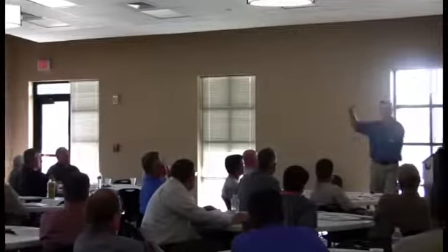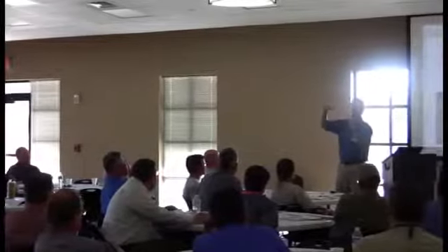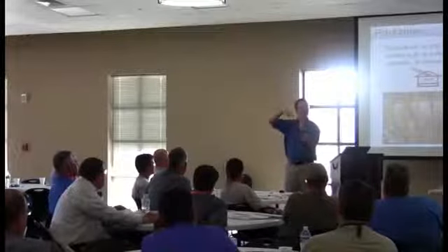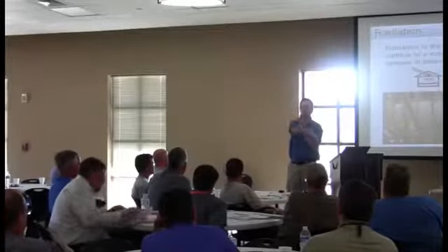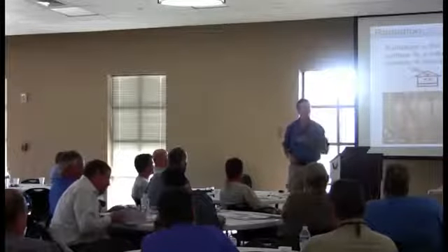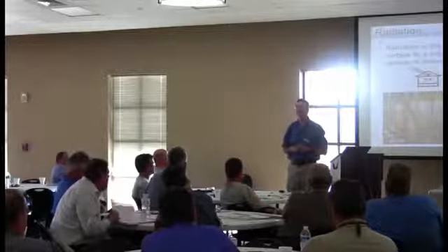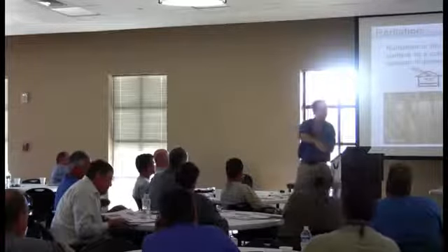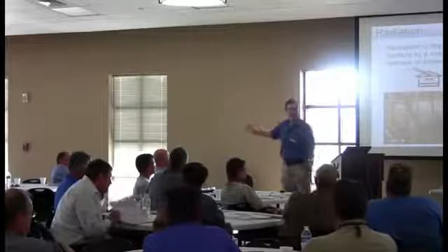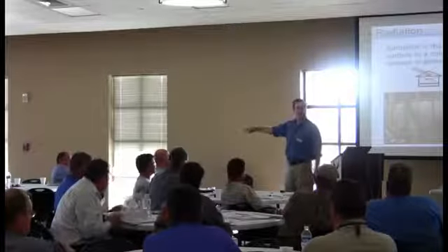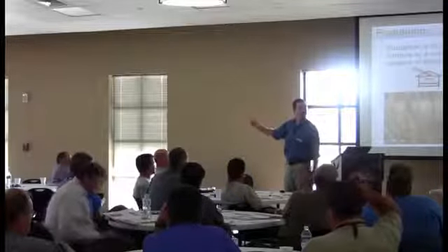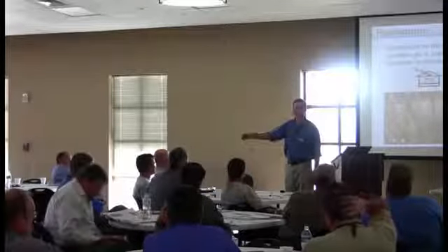When the sun hits a single pane window, some of the sun's energy is absorbed and reflected back, but most of the sun's energy is transmitted all the way through into the building. And in this case, the answer is 80%. 80% of the sun's energy passes through a single pane window. And so how many BTUs are getting in? Out of 10,000 hitting the window, 8,000 are coming in, right?